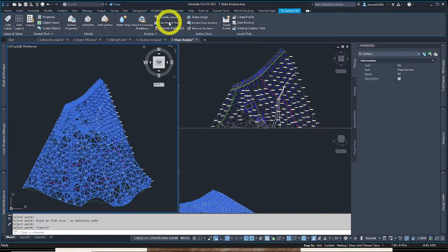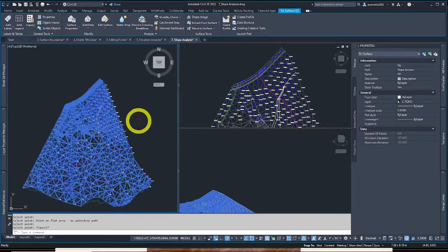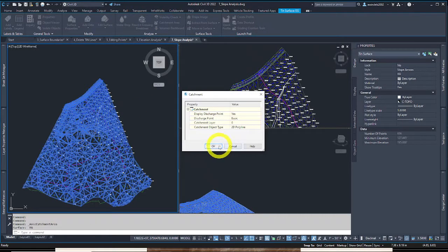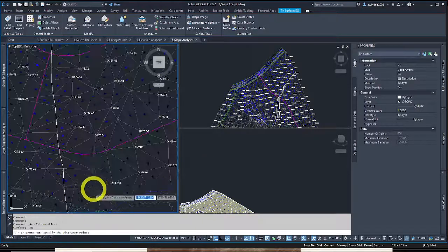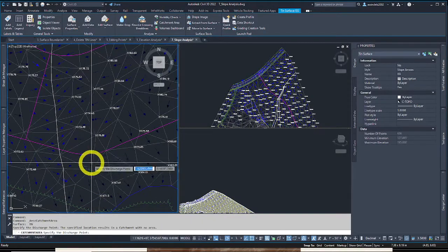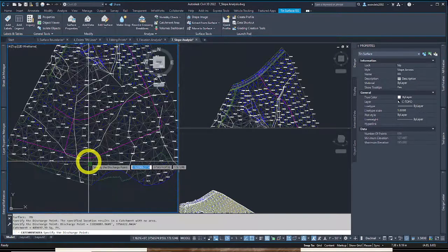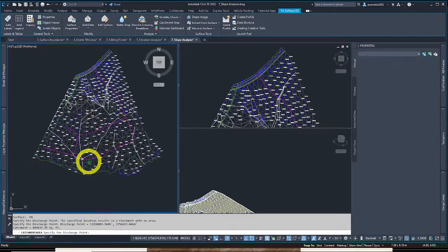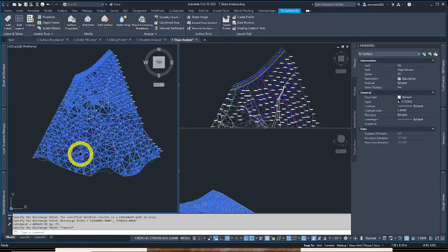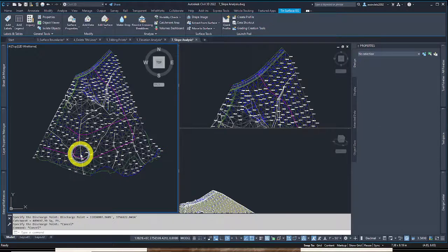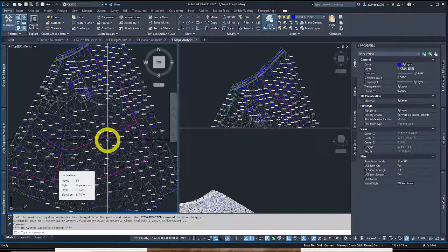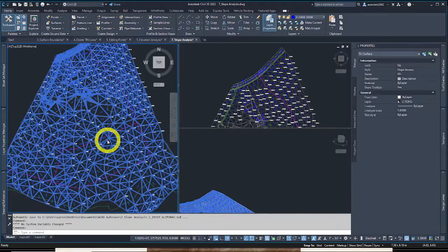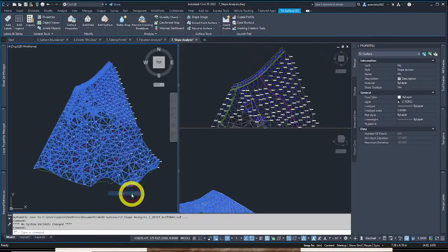Another one is the catchment area. I love using this one. So I pick a point on the surface. I've got to say what I want it to be first. Hit OK. Let me hit this theoretical point right here. First let's delete some of these. So I just deleted a bunch of those water drops just to clean this up a little. Let's change the surface properties a little bit.